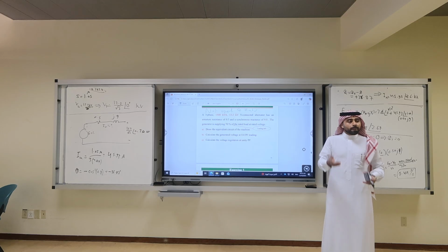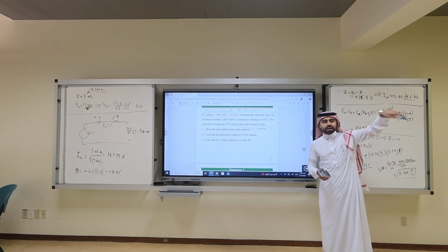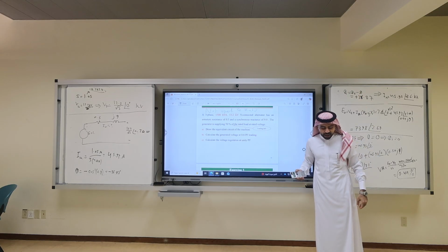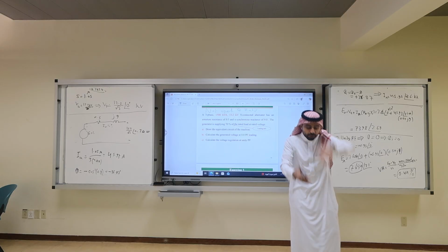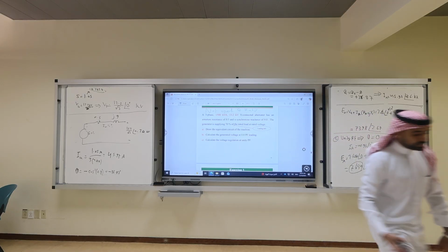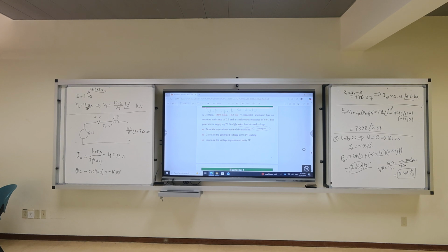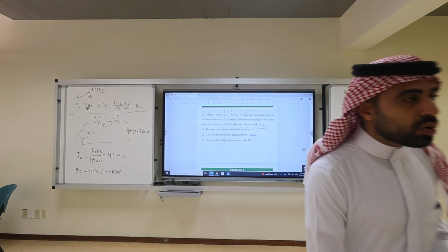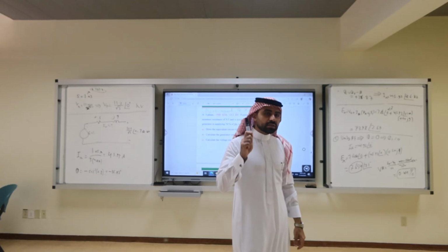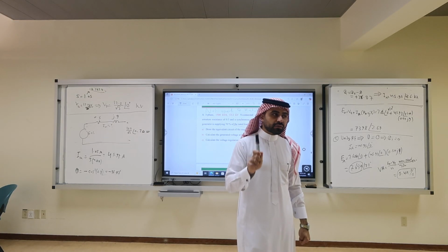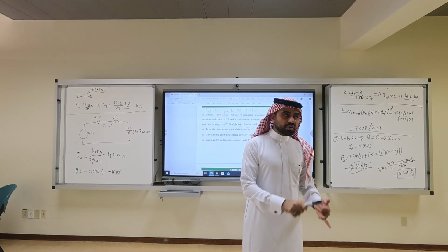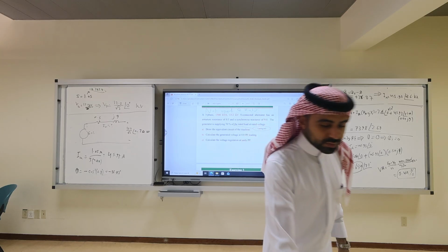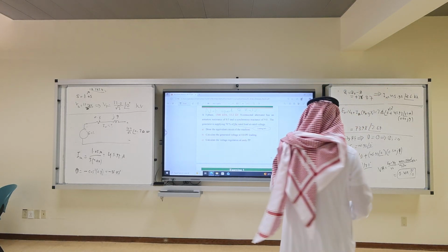The power factor. And isn't the power factor what changes the reactive power? Doesn't the power factor mess around with the leading and lagging, the angle, and the power triangle goes up or down? Yes. So question in the MCQ, what is the most important parameter that changes the VR for a synchronous generator? It is the power factor, whether it's leading or lagging, which is basically your loading conditions.